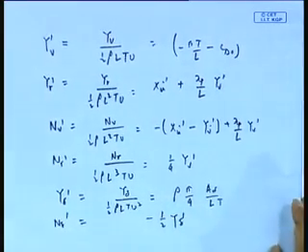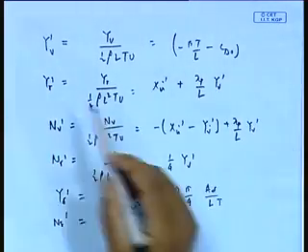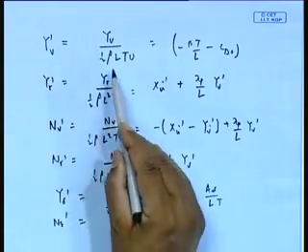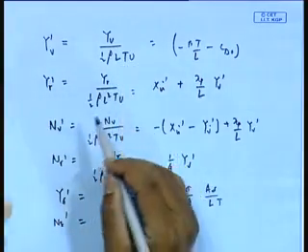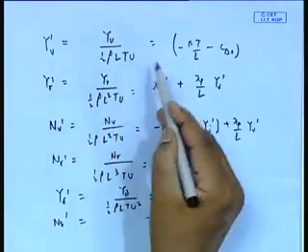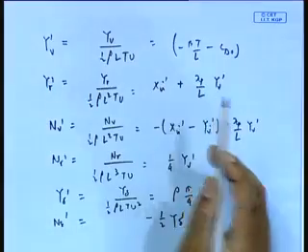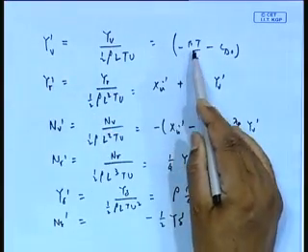See here, there is another set of estimated derivatives given. Of course, here remember that the non-dimensionalization is not L square but LT. Actually, one L has been replaced by T. Normally it was Yv by half rho L square T or L cube T, etc. But here, one of the L is replaced by T. There are different non-dimensionalization parameters. Never mind. But the point is that this formula here also is the same, minus pi T by L.